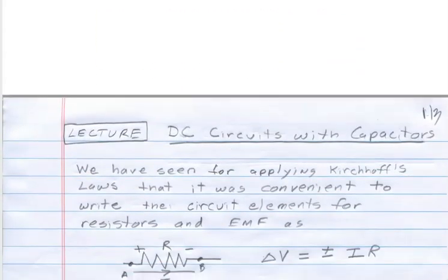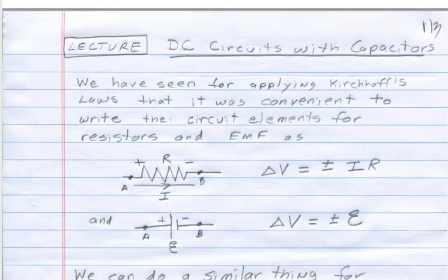Well, just to recall, we've got two circuit elements that we've explored in a little more detail. Voltage drop across a resistor: as we move across these, we use the general formula delta V for resistors equals plus or minus I times R. You have to have the direction of the current assigned as the positive current flow direction, and then you can mark the polarity, because positive charges always move from high potential to low potential.